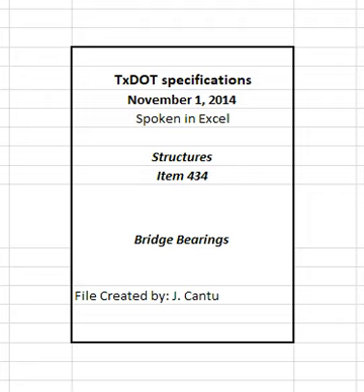3.3.4 Field Methods. Provide concrete surfaces for bearing areas under HLMR bearings in accordance with Section 420.4.9, Treatment and finishing of horizontal surfaces, unless indicated otherwise on the plans or the HLMR bearing shop drawings. Do not disassemble bearings unless otherwise approved by the engineer with the guidance of the bearing fabricator. Clean any contaminated sliding surfaces as directed by the fabricator.